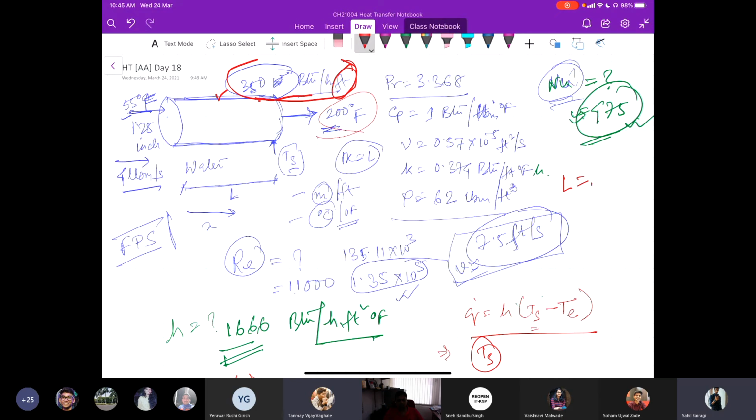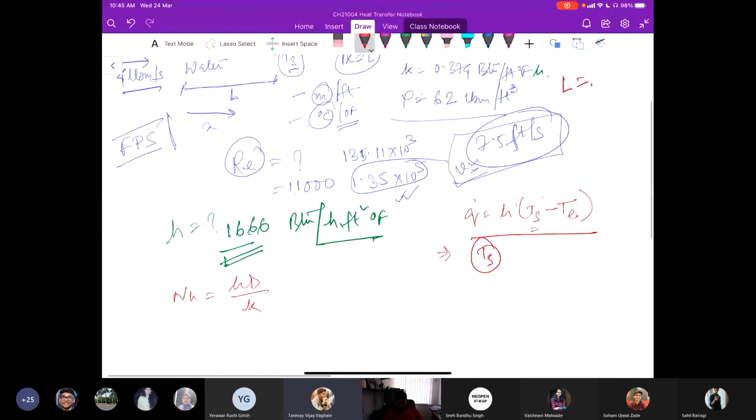So that surface temperature is 200.378 degree Fahrenheit. Absolutely right. So it's slightly higher than the exit temperature. I mean, it's almost reached its exponential plateau. If you remember the graph, the temperature at the exit was increasing. So that has reached the value of the mean flow temperature, just about 200 point something Fahrenheit, obviously.